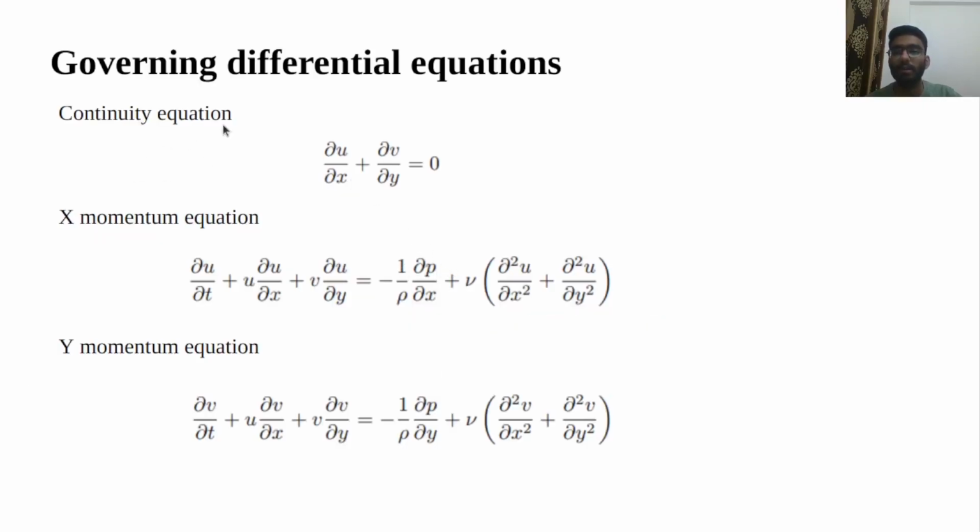We have the governing differential equations. As we are considering 2D flow, the velocity in the third direction, omega, is equal to 0. In the continuity equation the time varying density term appears, but our flow is incompressible, so density is not varying with time. This is our x momentum equation. For the 2D case we are also neglecting gravity, in both the x direction and the y direction.